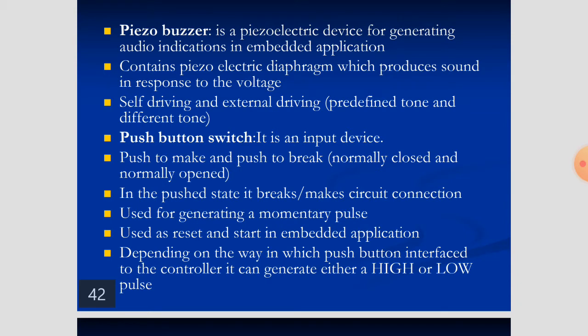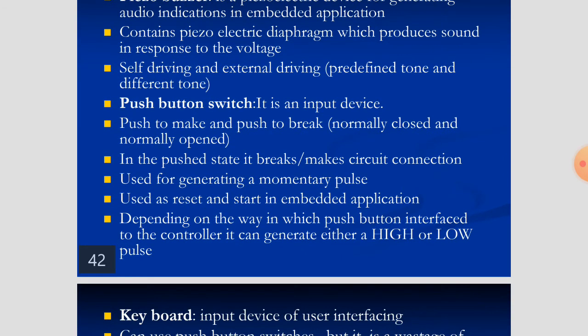Some of the piezo buzzers are self-driving, and some are externally driven. Self-driving means there are predefined tones already built in, so you won't get different levels of tones in self-driving piezo buzzers. You always get the same ringing tone in self-driving piezo buzzers, but in external driving you will get different types of tones.